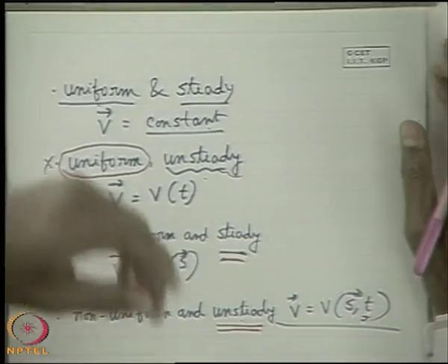This is the reason for which sometimes we choose axes properly to make many unsteady flow problems become steady. A problem may be unsteady in absolute scale, but if you choose the frame of reference against which the analysis is made, some flow may become steady. I can give you one very simple example which I have given in my book. If you go with a boat or a ship or a launch through a river, while you are sitting on the boat, you fix any point in the neighborhood of the boat or anywhere in the river, and you will see the flow condition is steady. You always see a similar type of flow of water surrounding the boat.